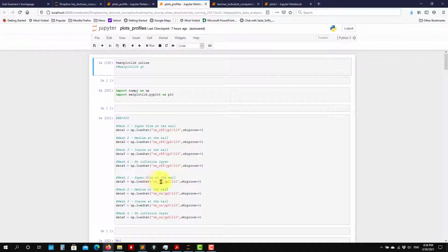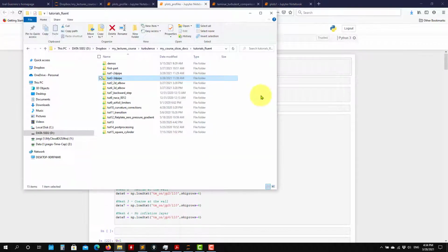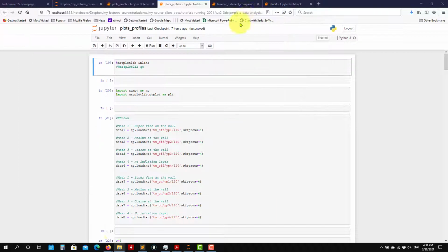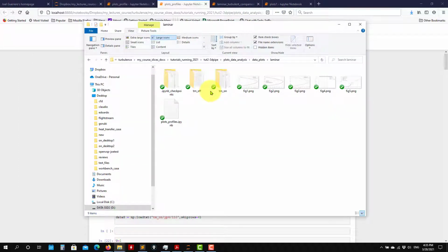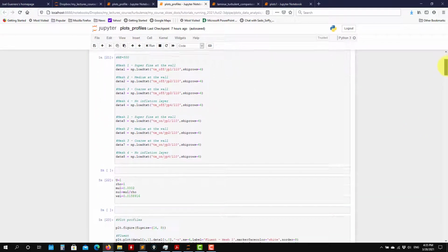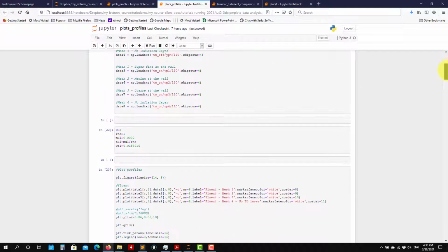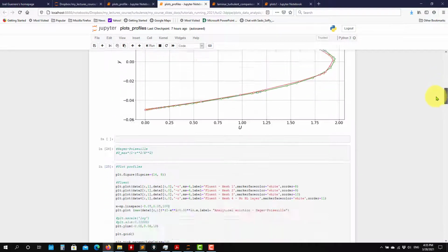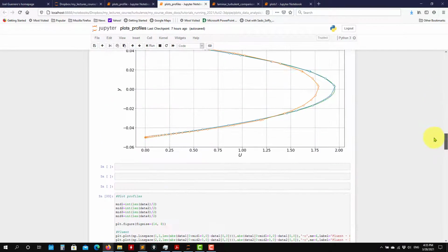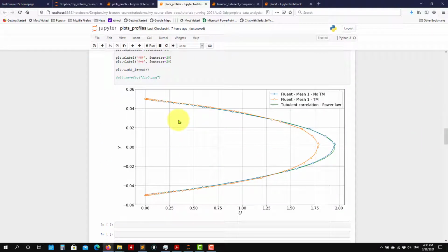When you see TN on in your data structures, let me go into that, it means turbulence model on, turbulence model off. What is mentioned there is that if you are sure that your data is laminar, there is no reason to run with the turbulence model on, and actually it will be slower because you are solving more equations, but also it might add some diffusion. Because the turbulence model is kicking in, it is adding that artificial viscosity, that turbulence viscosity, and you see here the influence, okay?